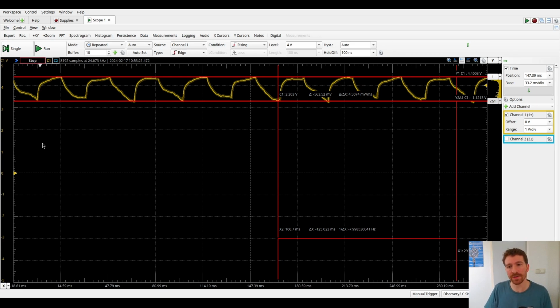And the nice thing about a photodiode is it responds much faster. Like you can see microsecond level changes using a photodiode. The difficult part about it is that you need to have a much more involved circuit that involves a transistor in order to amplify the circuit. It's a little bit less intuitive how that actually works, but it is doable, and there are schematics online and you can build it. And it is a great way, if you've got something that you need to measure that's going to be down in the microseconds, this is going to work way better. All right, so that's kind of it. I just wanted to share this technique with you.